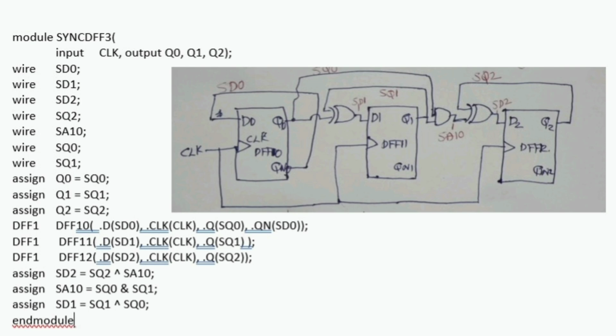This program uses structural modeling, and structural modeling basically uses instances. It shows the entire architecture as an interconnection of different sub-modules like flip-flops or combinational parts like gates and all.